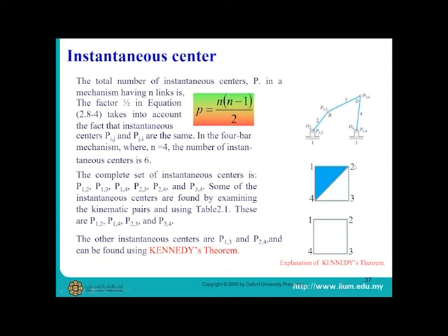The first triangle here connecting 1, 2 and 4 will give you the points P12, P14 and P24. Therefore, you need to create a line in the mechanism that connects these 3 points. You have points P12 and P14 here, but still do not have P24. Therefore, you need to extend the line beyond P12 and P14.